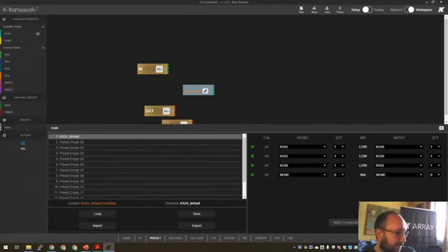So what I'm doing in V1, saying, okay, you are the subwoofer, KU26, please match with the Viper, KV52. The subwoofer checks what the high-pass filter on the Viper is, and automatically moves its low-pass filter to match it. So that's why it's very important to do the matching. Then you can save it as a device preset so that you can recall it from the touch screen, etc. All these functions are available also on the touch screen. So out of the box, you can actually forget the software.